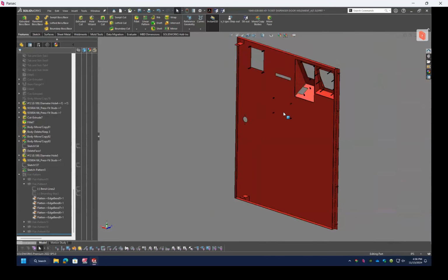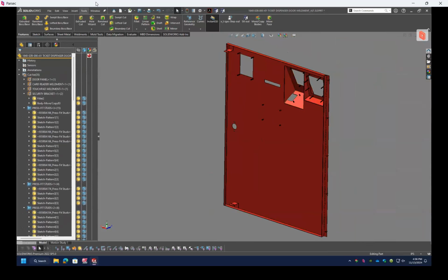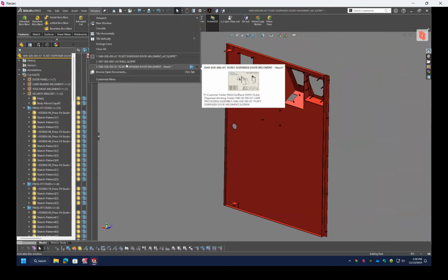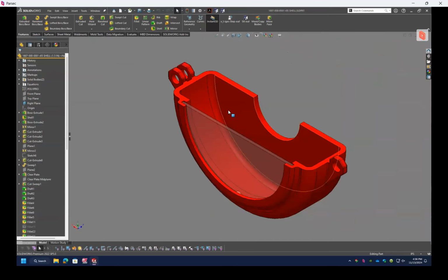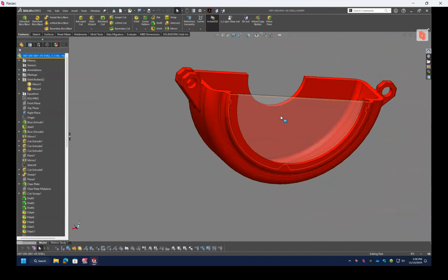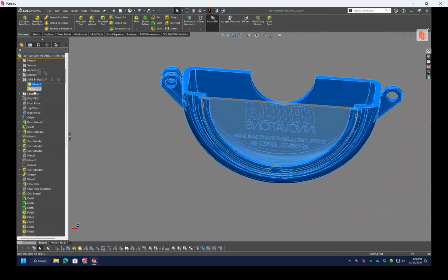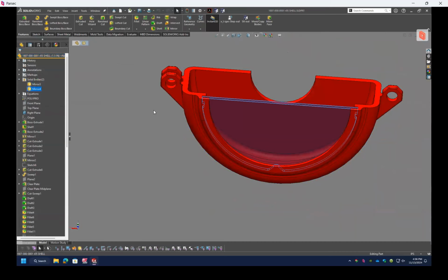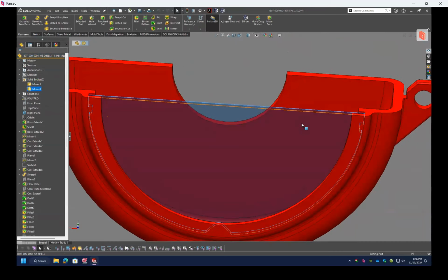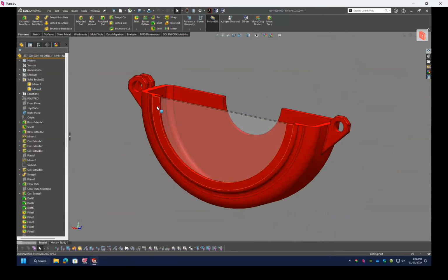So that's an example of how you might use that in sheet metal, and where you need to look out for properties and everything. And then I really just wanted to also show you, that's why I had this part up, another example. This is an injection molded part, and really there are two parts here: an injection molded one and a laser cut panel, or injection molded, depending on various factors. Essentially two different materials, two different manufacturing processes, but they snap together.